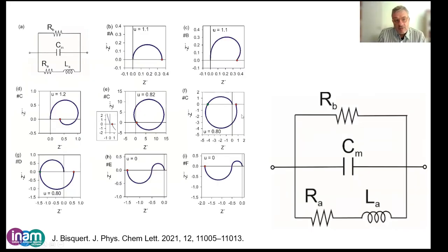The analysis of bifurcations is done by the small perturbation or linearized equation, and this can be converted into impedance spectroscopy, so that we have an equivalent circuit representing the dynamical model and several spectra that can tell us the dynamical regime at each voltage point in the JV curve, and this is the analysis that we present here.